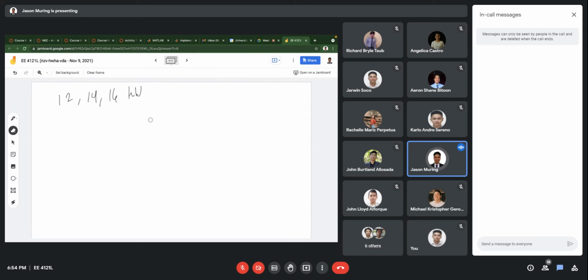So we can apply note 2. To calculate the total kilowatts according to note 2, we take the average of these three. Since 14 is the mean, that is also the average. So we consider that the average here is 14, and that there are three 14 kilowatt loads.